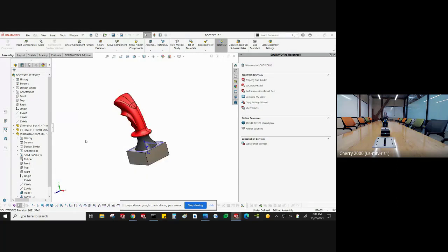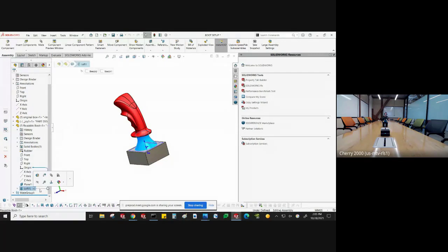So you can have parts like boots or cables, wires, belts, those sorts of things that now you can build top down so that they'll change when pulleys move or the spring gets compressed. You still can do that, but the nice thing is you can take that spring and you can use it in other assemblies and just say, no, instead of it being mounted here, now in this assembly it's mounted here, and it'll start solving with the geometry from that assembly rather than the original assembly. And you can see it puts this little parentheses around the external reference.